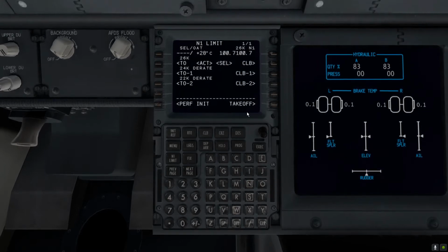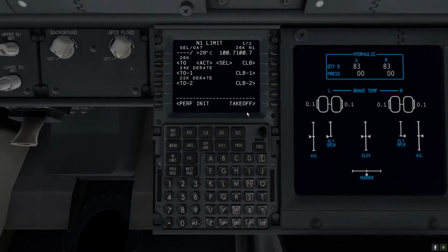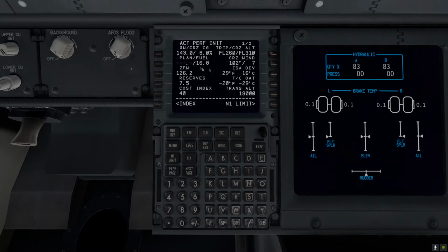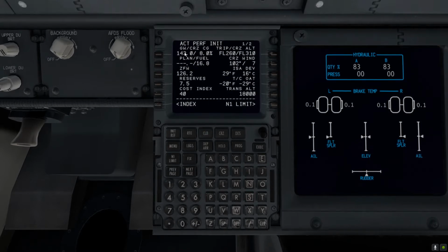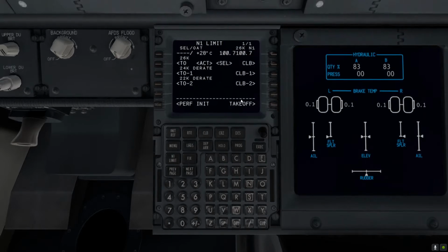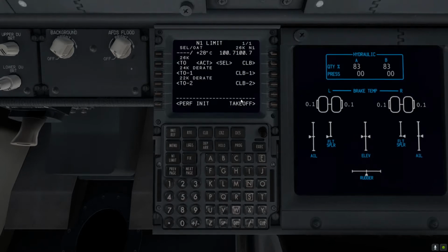So we go into our takeoff performance calculator. I personally use TopCat. I think I have already mentioned it before. Runway 01 left in Tampa with about 143,000 pounds. It was 143 in real life. What we do is to add 1,000 pounds or 500 kilos on top of this, but in the simulator there is no real need to do that because the weight that we are using and seeing are actual weights.